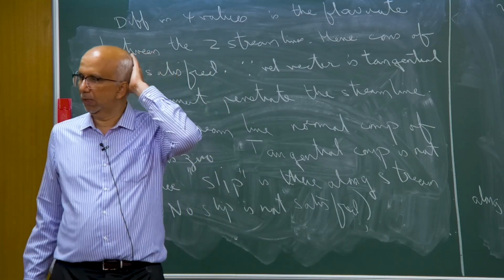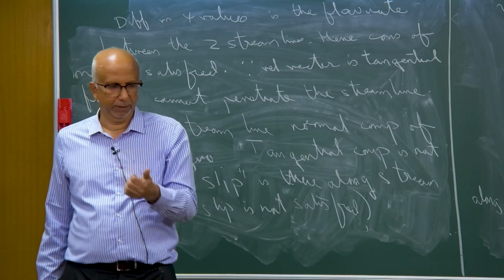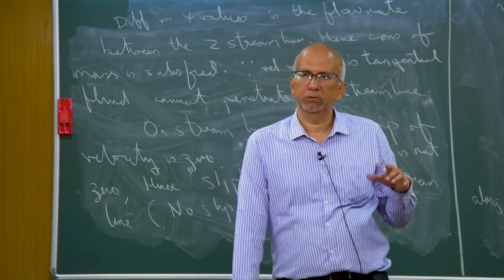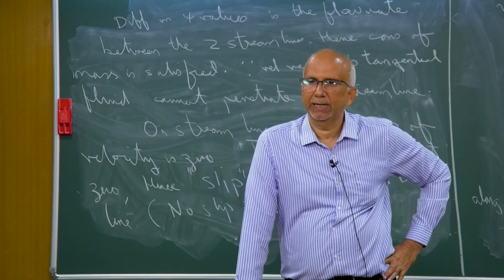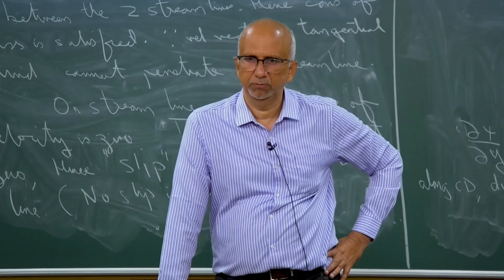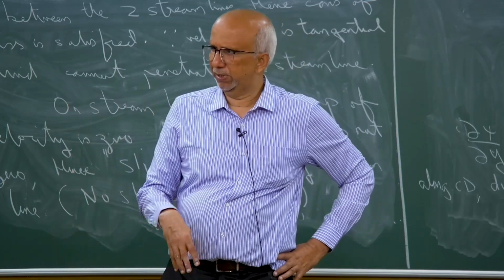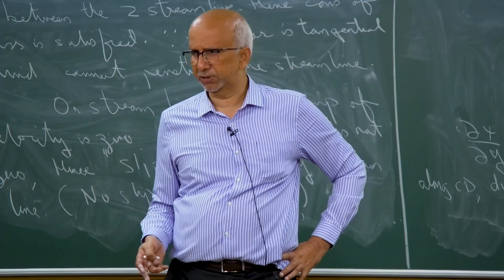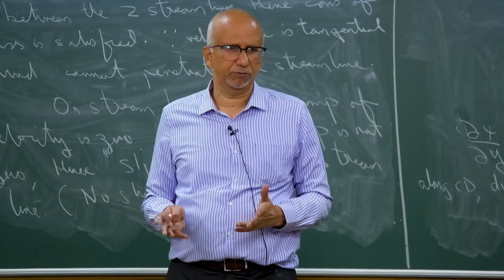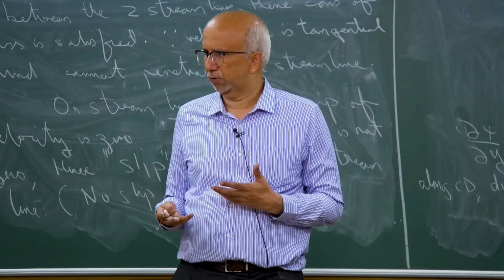So, what I have to do, basically now I have gotten your stream function and you know some of the properties of the stream function. So, tomorrow what we do is we know how the velocity is related to the stream function, vy is minus dψ/dx, vx is dψ/dy. You go to the momentum equation, substitute everything in terms of stream function, eliminate pressure like I described, and you will get one equation for stream function, and that you can solve for, okay.